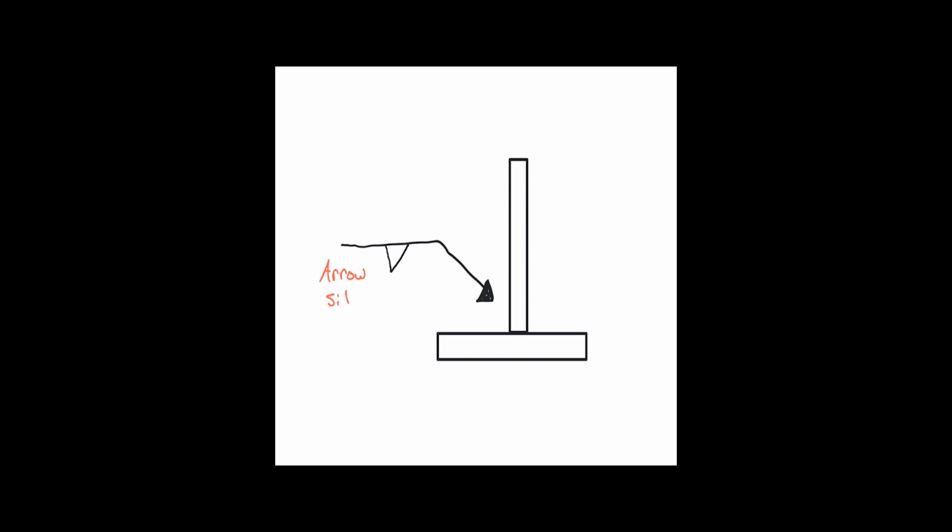If a weld symbol is on the bottom of the reference line, that is still the arrow side. So where the arrow is pointing to is going to be the joint where you place the weld. And if you're given a weld symbol on top of the reference line, that still means other side. So no matter in which direction the reference line is being drawn from, or whether the reference line is pointing up or down, the side significance never changes. Bottom of the reference line is always arrow side. Top of the reference line is always other side.